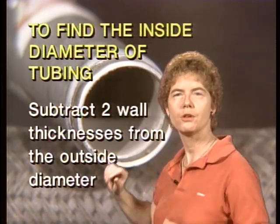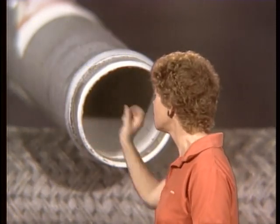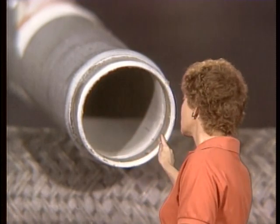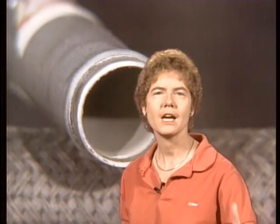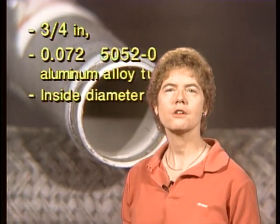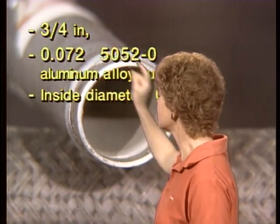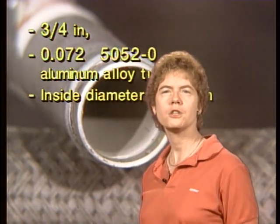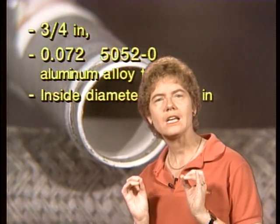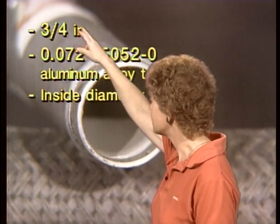Metal tubing, as opposed to flexible tubing, is measured according to the outside diameter, and then you've got the wall thickness, and if you want to know the inside diameter, what you have to do is subtract 2 wall thicknesses from the outside diameter. And here is an example that the FAA might give you. They'll say to you that you're going to make a replacement oil line, and it is 3/4 inch 0.072 aluminum tubing, and it's 5052-0 aluminum alloy tubing. And the question is, what is the inside diameter of that tubing? Well, 3/4 inch tubing is the outside diameter.